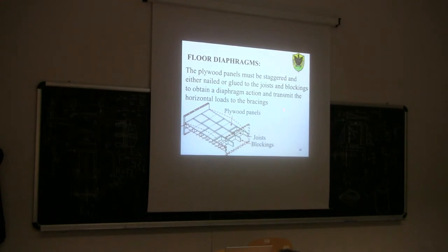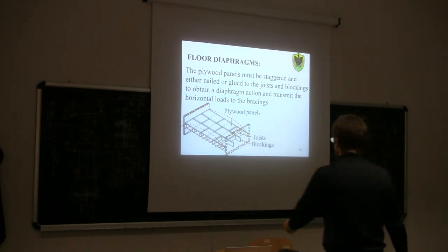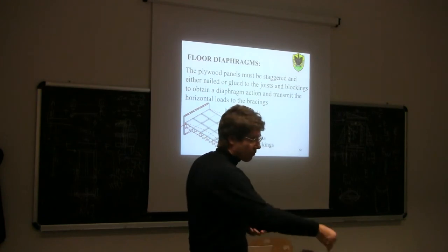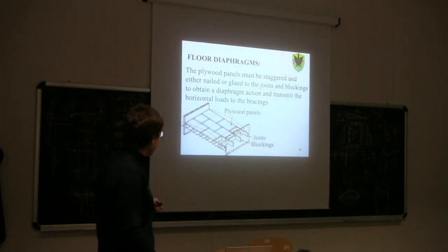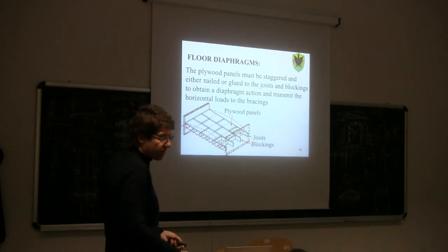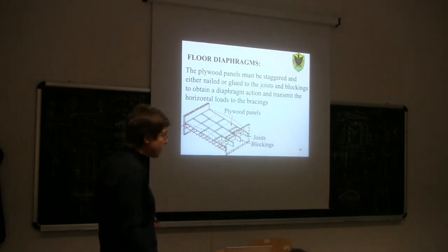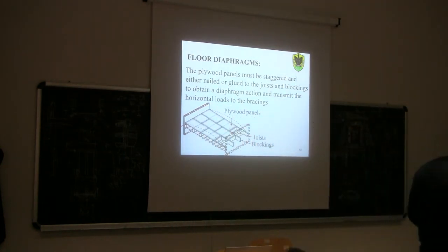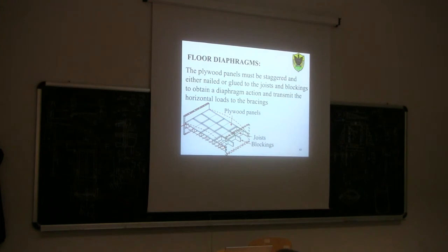So in the end, this system would be what we call in reinforced concrete design a one-way, two-level system. Because there is here one sheathing, which is in some way spanning across the joist, so subjected to bending, and transfers the load down to the joist, and the joist has to be loaded in bending. So those nails, in terms of vertical loads, are not very much stressed. So I would say that the stress in those nails due to vertical loads is almost negligible. That would be just ignored. Okay? Is that clear or do you have any doubt?